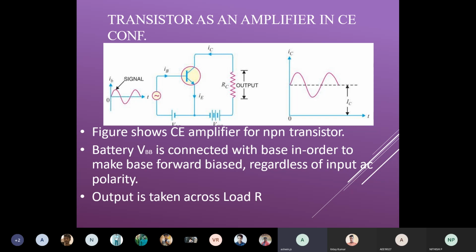Guys, same like open circuit and closed circuit. Now it is made as closed circuit. Closed circuit means the current is flowing, but the voltage becomes less. Once it is open circuit, I mean the transistor is not switched on, it is in off condition. At that time there is no base current to drive the transistor, so there is no current flow, and the output will be equal to the voltage given to VCC. Is it right or not?